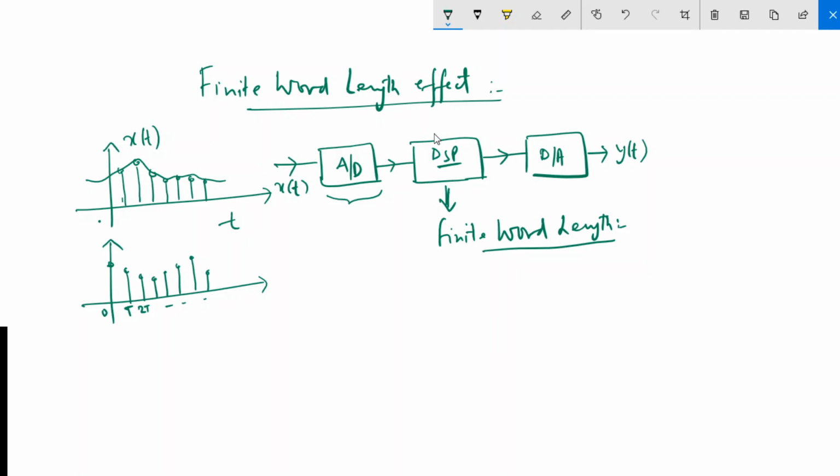So your discrete samples. Time is now discretized, and this is basically done by a circuit called the sample and hold circuit. The sample and hold circuit actually acts like a switch. That means at any particular time, it samples and it holds this amplitude till we get the next sample. Because to convert this analog signal into digital, you require some time. So till that time, you have to hold the signal amplitude till this sample is converted into a digital format.